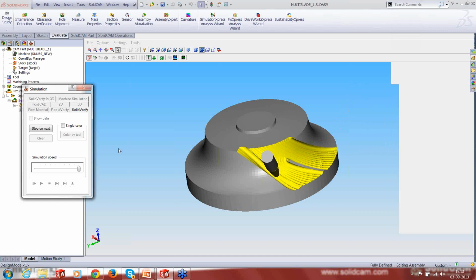Okay. So it's kept about 0.35 material on the sides, which is what I have asked it to keep, and it continues to rough down. We can see an image of this rough down later because it's going to take a couple of minutes more and we have a lot of things to cover. Right, so I'm going to pause the simulation and come out of it.